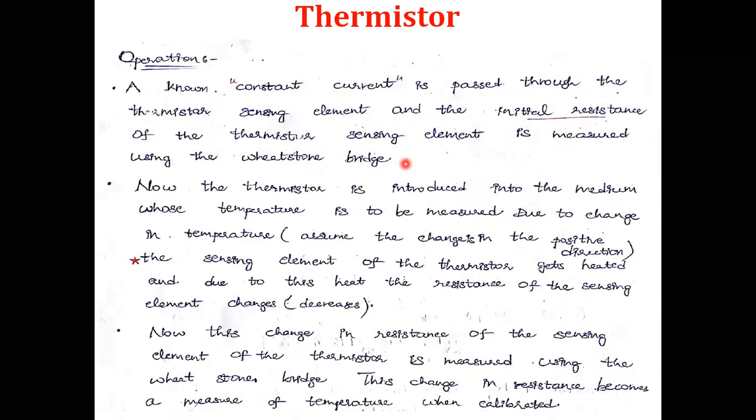And the initial resistance of the thermistor, we are going to measure using that Wheatstone bridge. Now the thermistor is introduced into the medium whose temperature is to be measured.